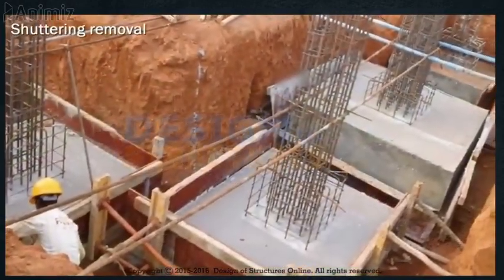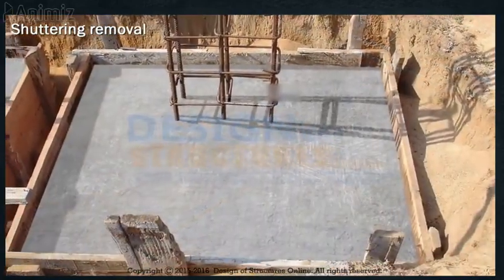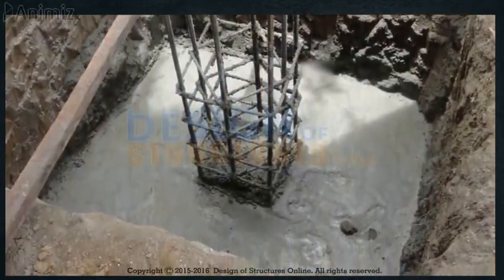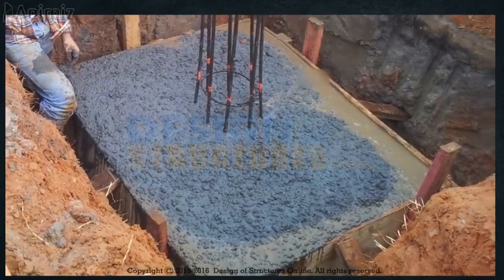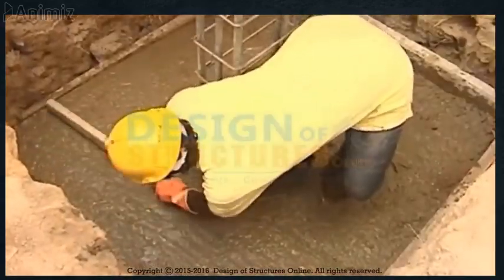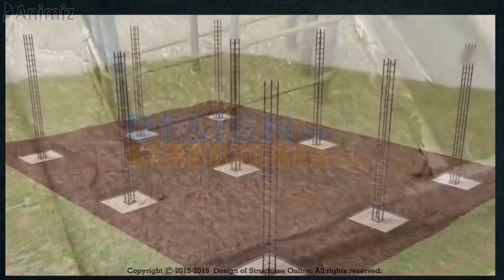Shuttering removal. The formwork removal procedure should be supervised by the engineer to ensure the quality of hardened concrete in the structural member. That is, it should be free from, or have minimum, casting defects such as honeycombing, size and shape defects, etc. These defects in concrete influence the strength and stability of the structure. Thus immediate repair works can be done or the members can be rejected.